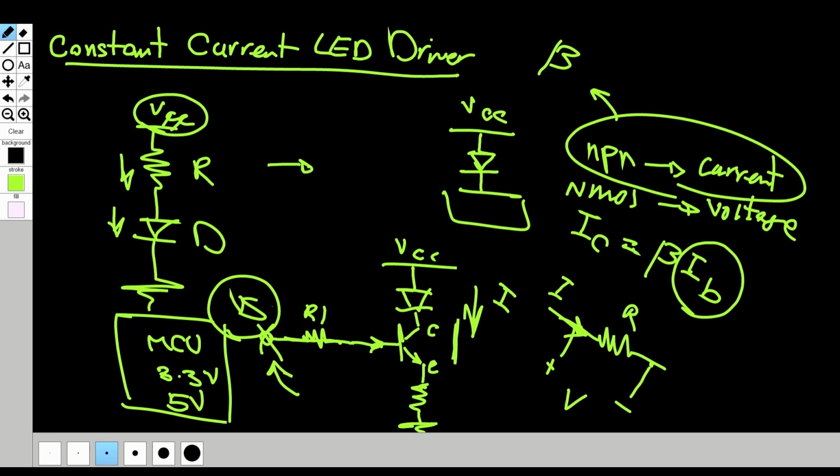So the way that they do it is basically the sensing circuitry. What it does is it says, I know that the current through this is just simple Ohm's law, V over R. So I know what my R is, and whatever my voltage is, that voltage could be a simple reference voltage.